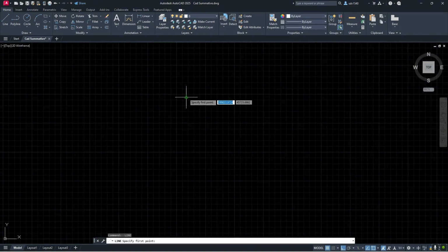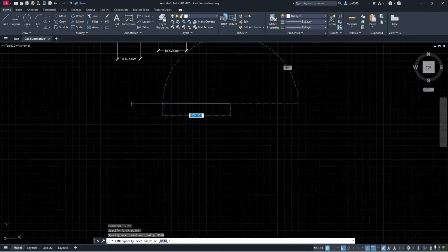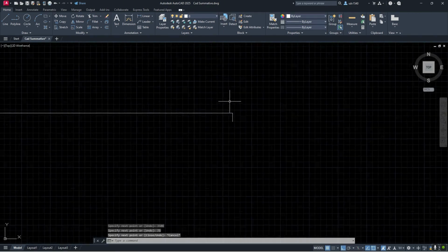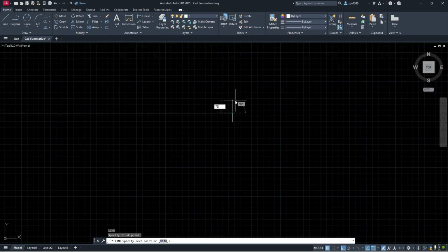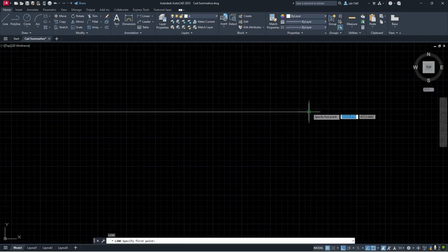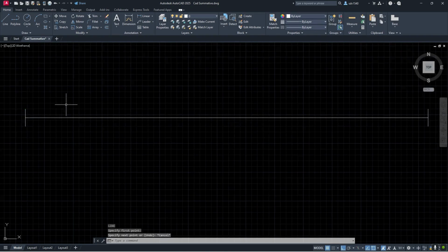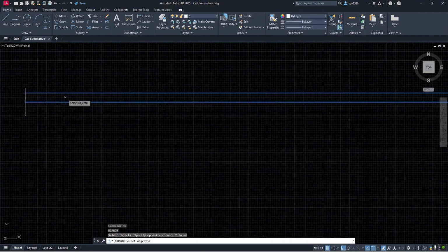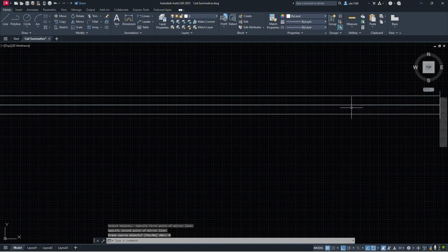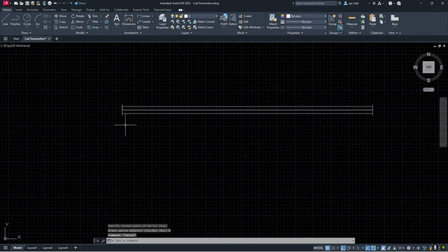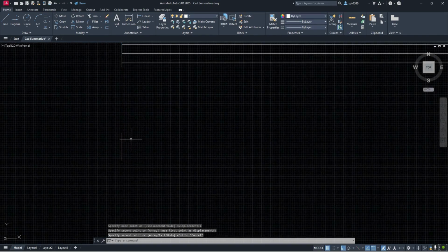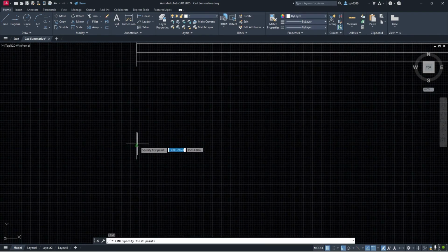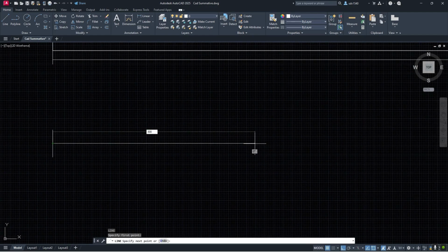Our first window has a length of 3,500 millimeters and is represented by 2 rectangles, each with a width of 50 millimeters. The lines on the side are so that we can attach it to the center of our 150mm thick walls. In creating the window itself, we will be utilizing the mirror command, and the copy command will be used to recreate the windows for the shorter lengths.